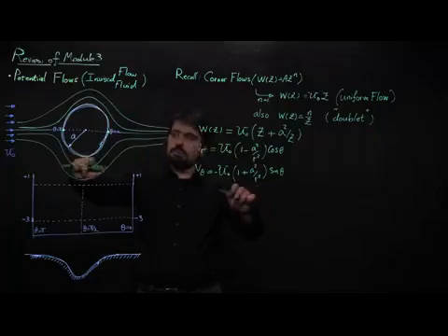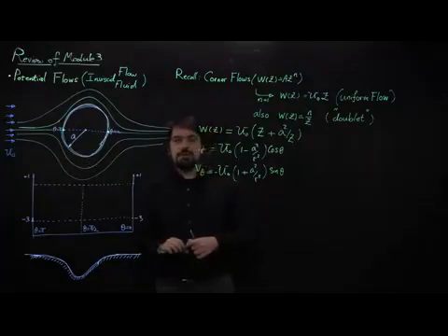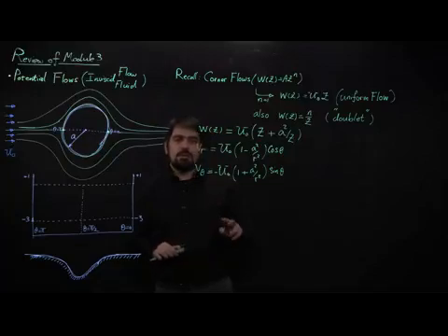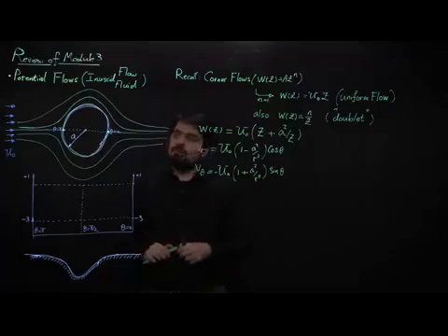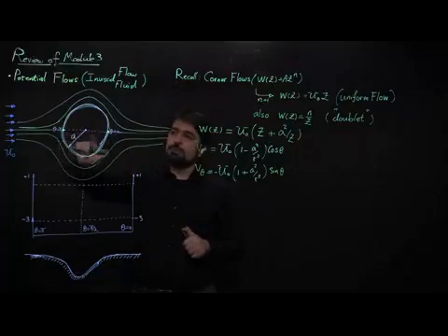In potential flows, we don't have the no-slip condition anymore. We cannot really satisfy the no-slip boundary condition because we have reduced the order of the differential equation by one degree by ignoring the viscous terms. So we indeed have v thetas that are non-zero. There are, however, two points where both Vr and v theta, or in other words the overall velocity vector, become equal to 0.